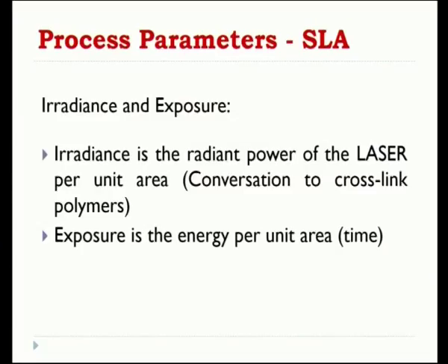I may give an input of, for example, more than 1000 kilowatts or 5000 kilowatts, but the particular material has a limited capability to absorb that energy, right? We cannot keep on giving energy to the material, and it is not going to absorb everything or convert the entire process until we reach the final exposure, right? What is the final limit here? It is the conversion from one state to another, monomer state to polymer state, or liquid state to solid state, by forming the complex cross-linked polymer state. So how much energy is required, that is what we need to calculate.